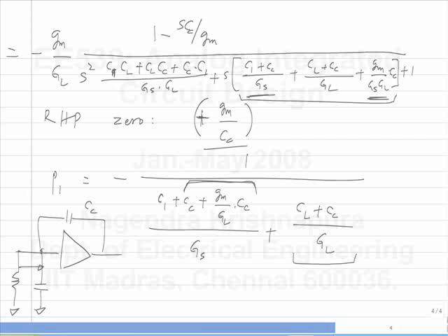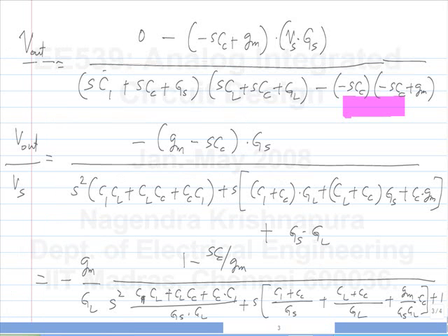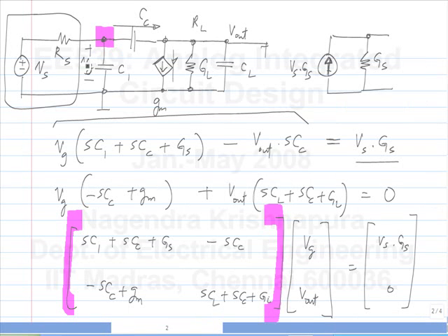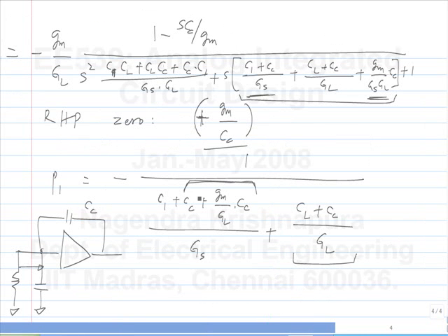So, across the conductance GS, you see C1 of course, because it is directly connected, and you see the effect of Cc, which happens to be a Miller multiplied version. Okay. So that is largely what forms the first pole, if Cc is significant. Otherwise, because we have an imperfect amplifier, we have this extra term also.